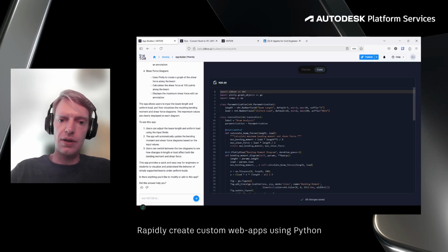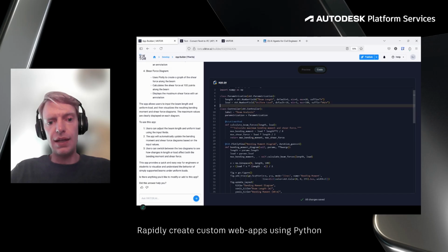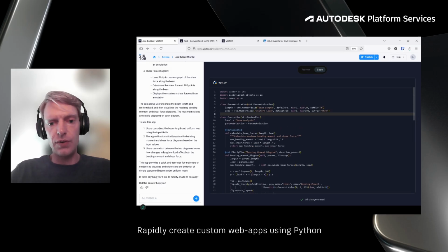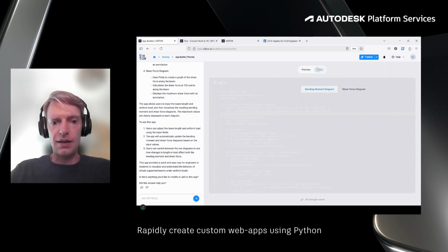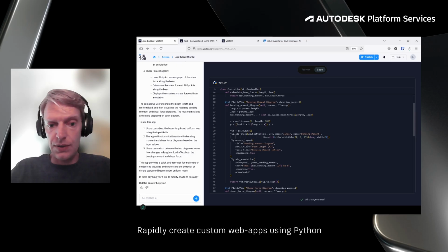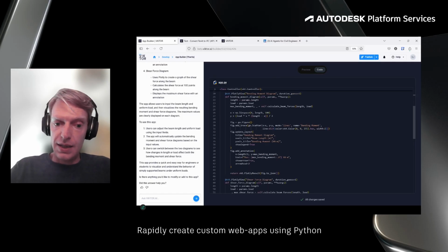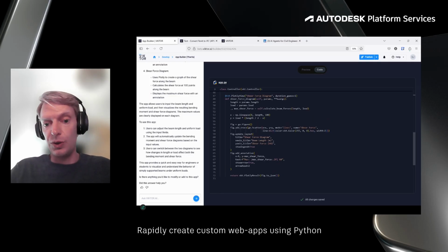So what's now behind this, and that's what I refer to as the VIKTOR code. What you see over here, we have a VIKTOR Python package. And this is actually the code that it generated. So first of all, it created these two input fields. These are the fields that you can see here on the left-hand side. And next to that, it created the logic. So here you can just see what it generated. It calculates the maximum bending moment based on a Python function it created. And here you can just see all the logic which is there.